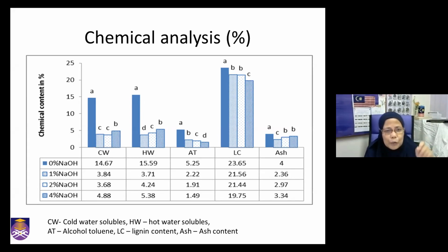There's a lot of chemistry that goes into this, because sometimes when you want to remove something, you have to be very careful, because you will remove at a certain concentration, but after a certain concentration, you have a negative reaction. So there is chemistry behind this. I'll have to work on why that happened. But what this says is, if we were to do this processing of the material, don't go overboard. Just go for about 1 to 2%, and that should be good enough for you to clean up your fiber for the process.